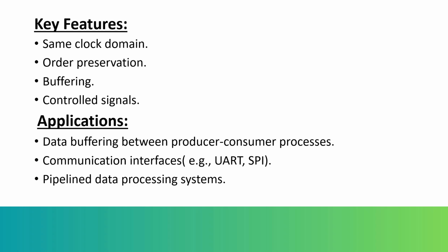We use synchronous FIFO for simpler designs. Here are its key features and applications. Key features are same clock domain, order preservation, buffering, and control signals. Its applications are data buffering between producer-consumer processes, communication interfaces, and pipeline data processing systems.